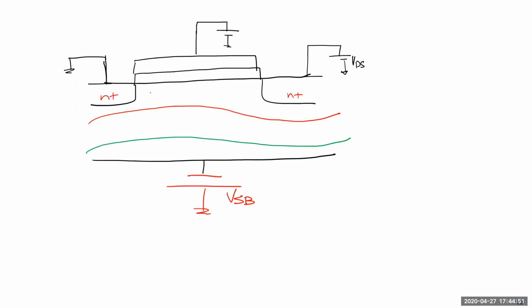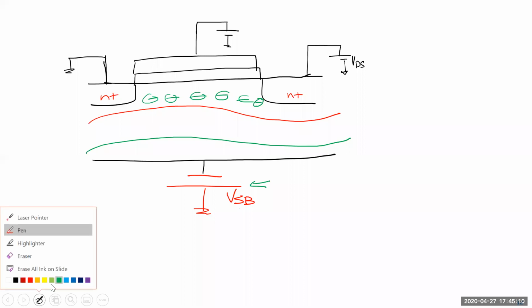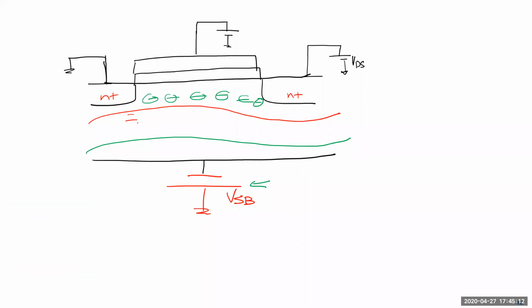So basically, what you're saying is that you originally had this. Now I added this substrate bias, which I think Puneet is right, it's better to explain this, although we don't do this in the circuit. So I apply a negative substrate bias. Because of that, my new charge is this.